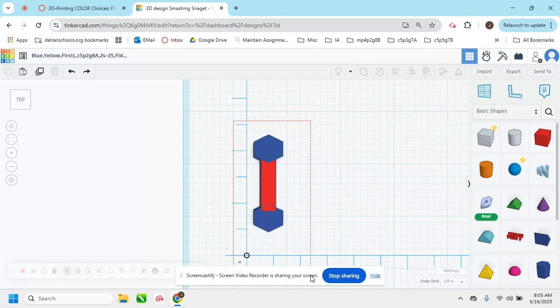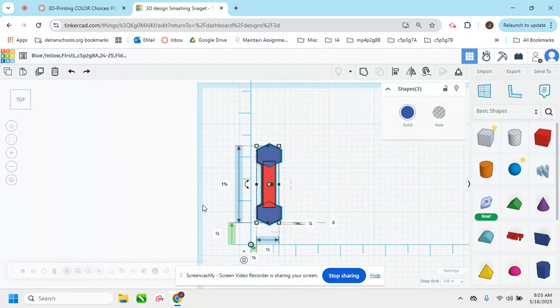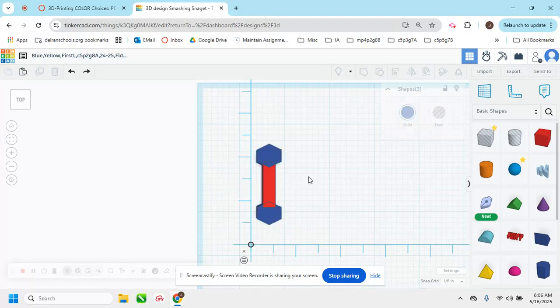I want to make sure that these two are perfectly balanced, and that looks good. So before you go and rotate and copy, it's really important to have this spoke balanced on all sides, okay? And you want 1 at each end if you're doing even numbers, okay? So like 2 or 4 or 6, 8, things like that, okay?